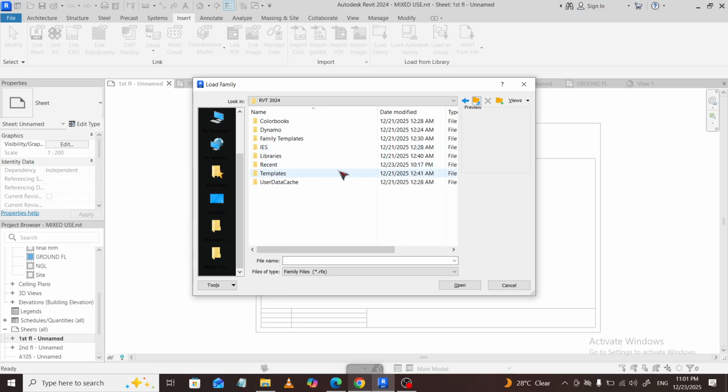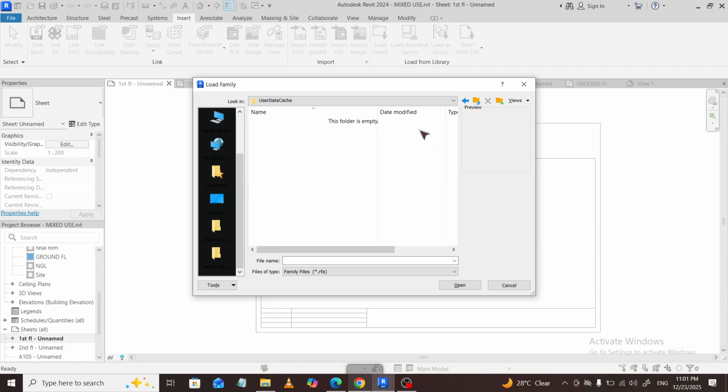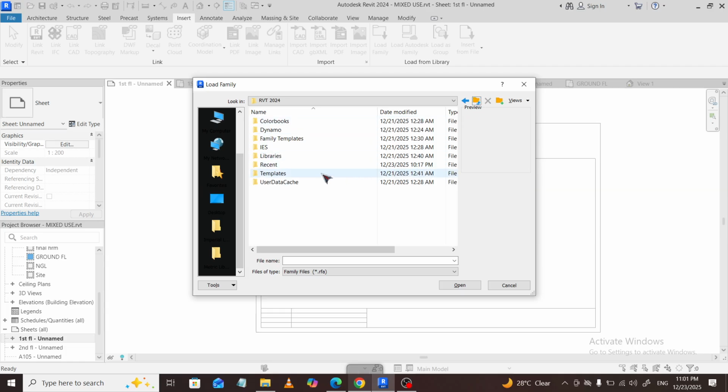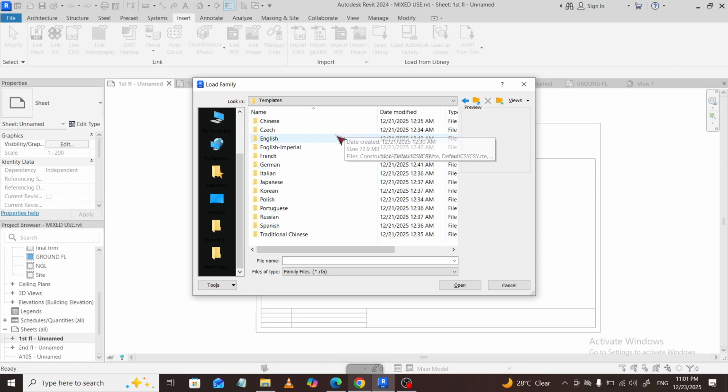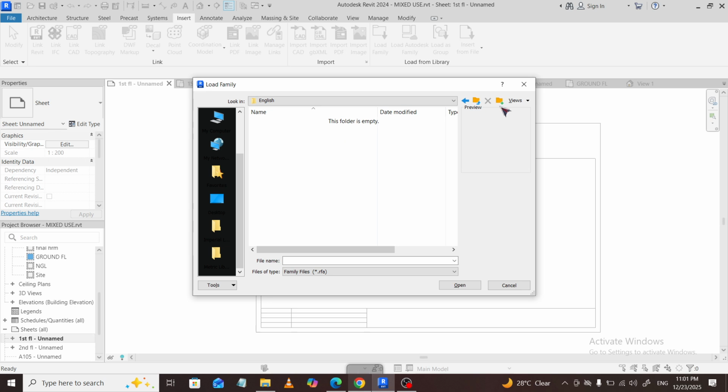Now, to align the arrow with your project's true north, select the North Arrow symbol, then click the Rotate tool. You can either enter a precise angle in the options bar or rotate visually by picking a pivot and a reference line. If your project uses both Project North and True North, confirm which orientation your documentation requires.